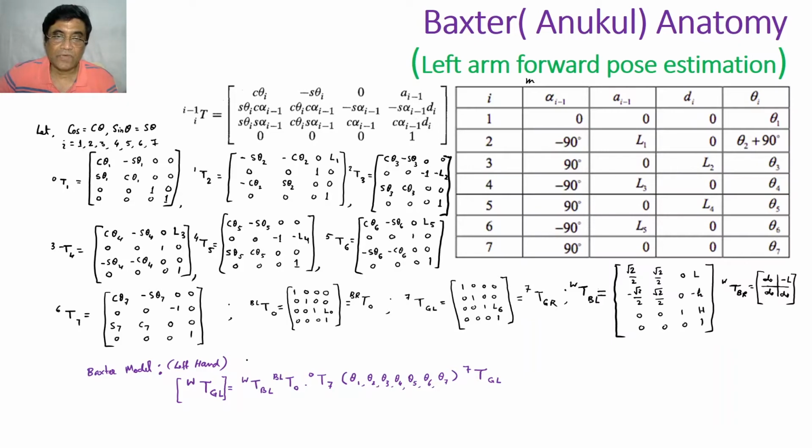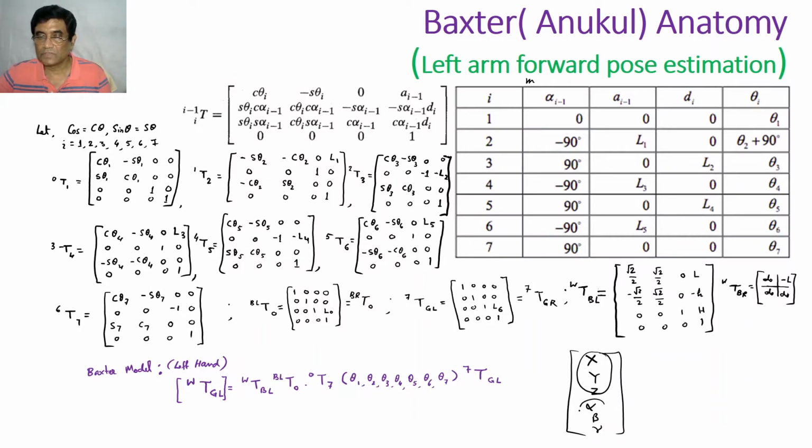So now this is what I already have: the model. This is the forward kinematics model, and I have brought it here so that you will get that ground with respect to link 7. Baxter has 7 joints, and in 3D Cartesian space, how many degrees of freedom are possible? By this time you know, this is 6, right? What are those 6? X, Y, Z, alpha, beta, gamma, or theta, phi, psi, whatever. These 3 parameters correspond to position, and these 3 correspond to orientation.